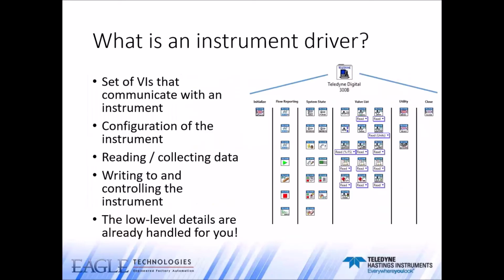LabVIEW can control devices and receive responses from them. To perform this, an interface that enables LabVIEW to connect to the device or instrument is required. These interfaces are called LabVIEW Drivers, and there is a vast library of them available within the LabVIEW ecosystem. Some drivers are developed by NI, while others might be developed by the manufacturers or third parties.